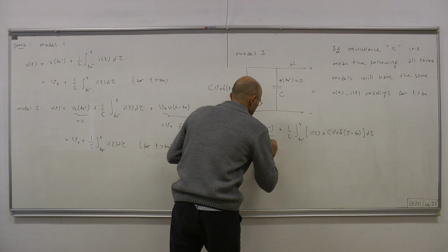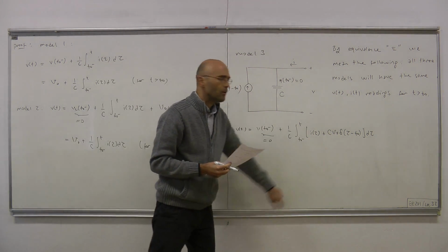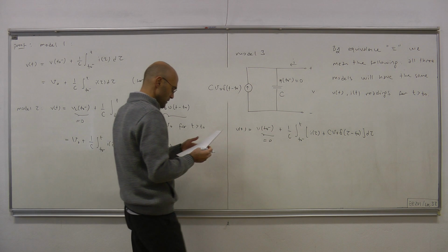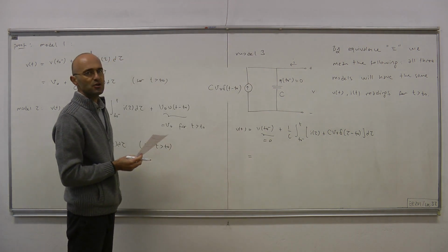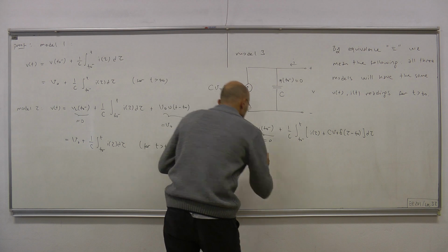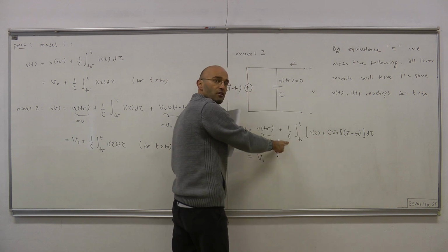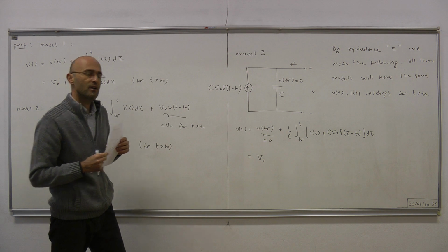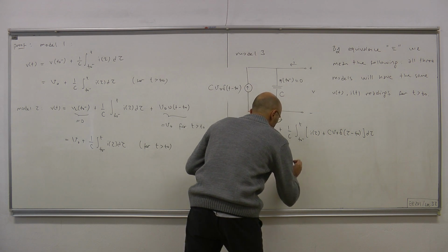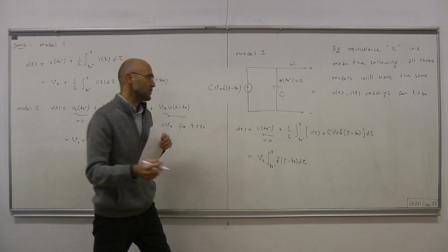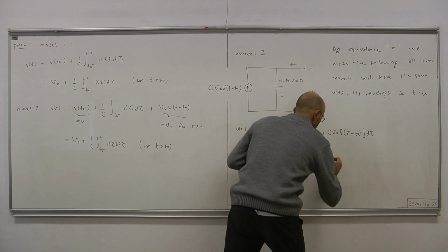Okay, first of all, this thing is 0 by assumption because this capacitor is empty. And then now let's work out what that integration gives us. So that equals, let's separate the integrand and write that integral as 2 separate integrals. Okay? So what we have is V0. We can take this C V0 out. This C will cancel with this 1 over C, and we will be left with V0 multiplying the integral delta tau minus T0 d tau plus we have the integral of the current 1 over C T0 to t, I tau